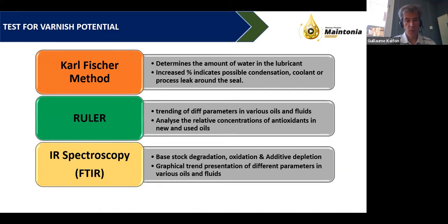Water, you always want to know water. So this is what is called here Karl Fischer, a water analysis, particularly naturally for steam turbines. So this is a key test. And then you need to understand.